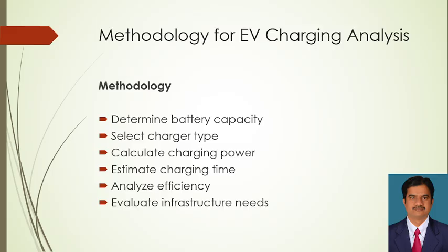Remember, if it is a very high capacity, with a charger rating of 35 to 50 kilowatt, in terms of the motor or capacity used in the electric vehicle, we cannot connect that battery to the single phase supply of 230 volts. So we need to know the capacity of the battery. Based upon the capacity of the battery, we decide whether to connect to level 1, level 2 or DC fast charging. Remember.